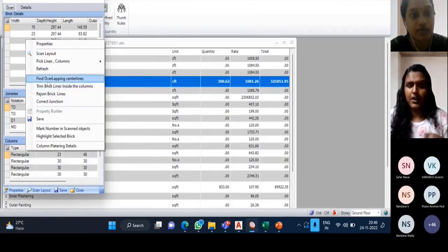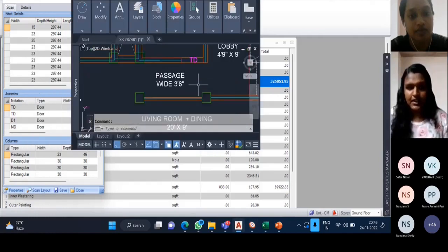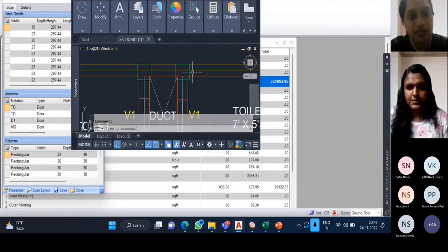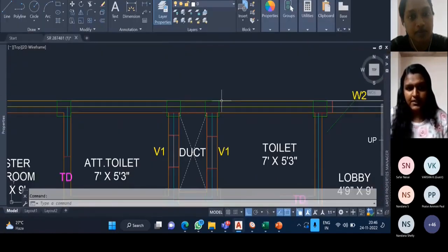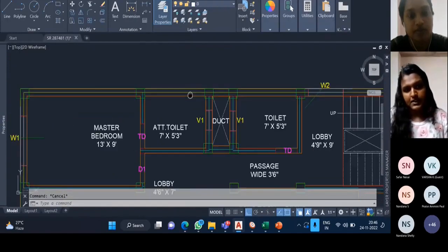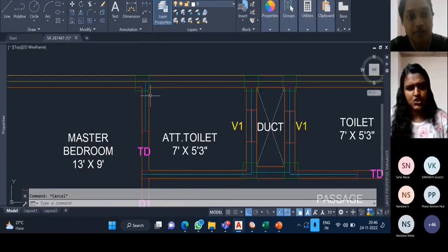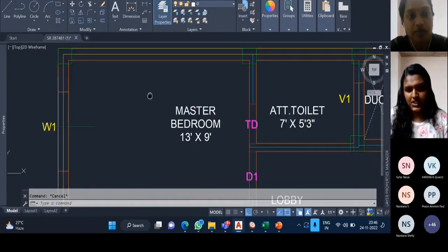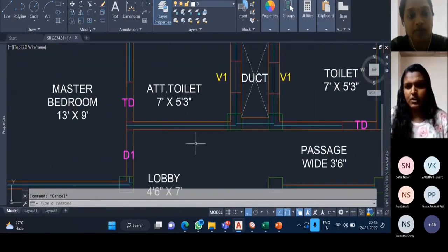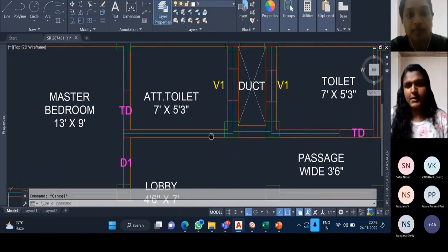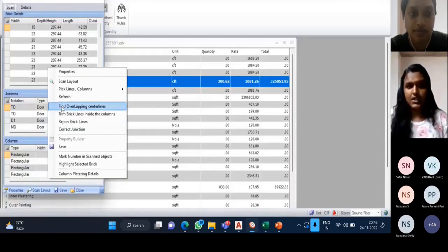The basic reason why we are providing these corrections is that in the drawing we can see the center line is generated right now, and the center line is passing through these columns. There should be corrections for the junction here. Manually, we know that there is a junction correction in the estimation process. So in order to trim out those center lines, we have to do these 4 corrections.